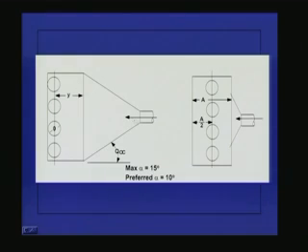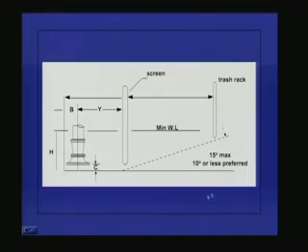For example, one should go for a sump design of this nature or a sump layout of this nature compared to this. This kind of a sump design is not recommended at all. If you look at the elevation, the water will be flowing in this manner from this side to this side. Ahead of the pump, we need to put a trash rack.